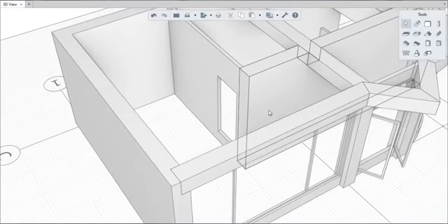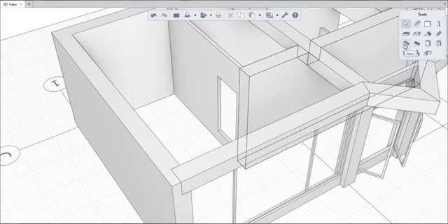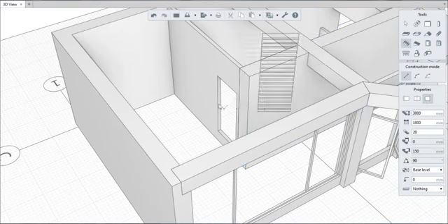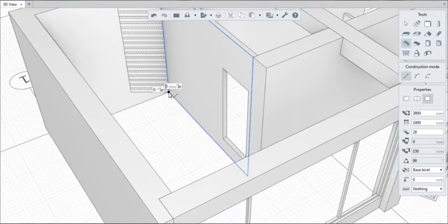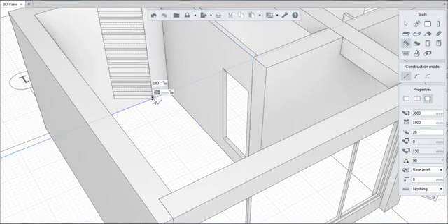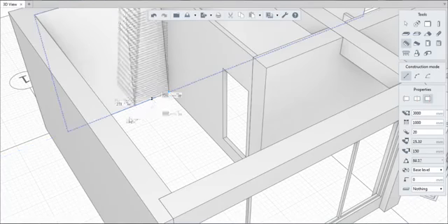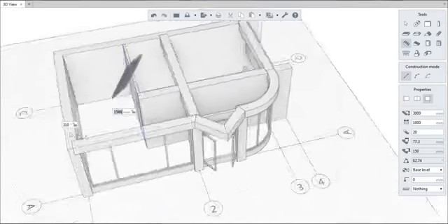Build up the stairs from the ground floor. Select the Stairs tool and then set the required properties. Mark off the first point 1000 mm from the intersection of the wall and the partition point. The second point is at the intersection of partition walls.